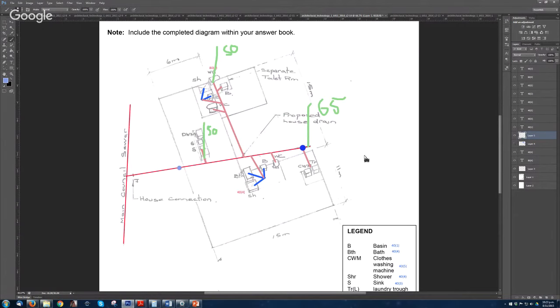That's the only place you need overflow relief gullies, the laundry and the kitchen. That's it. You don't need them for the bathrooms. Usually that's where you would have the most chance of blocking, because of the fluid and the detergent, stuff like that.